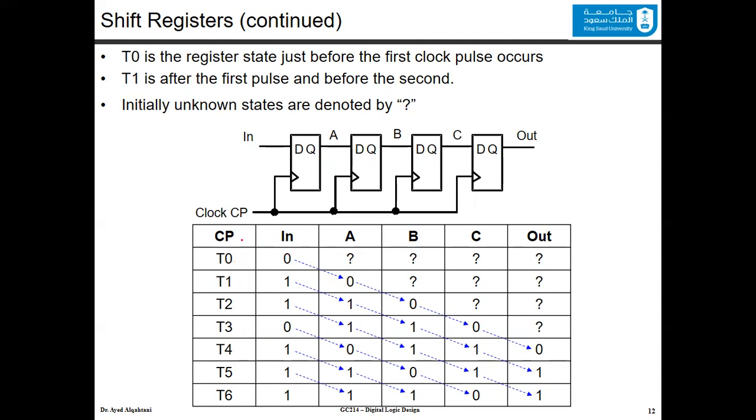And you can see, if we have these inputs here, after 4 cycles, cycle 0, 1, 2, 3, then in the 4th cycle the first input 0 would show in the output, followed by 1, followed by 1, followed by 0, and then the new input would be 1.